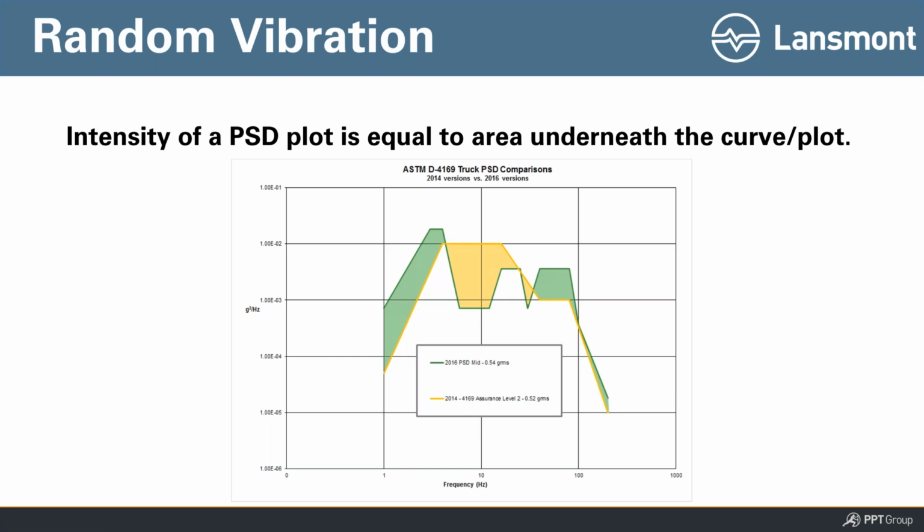So yes, the overall GRMS of those profiles is similar, but you really need to think of these tests in terms of where across that frequency domain the energy is being input to the vibration test table, and then eventually into your test products. Because these are not equivalent. And one could cause you a lot more problems than the other, depending on whether your products or unit loads have sensitivity or resonances or respond at those frequencies.